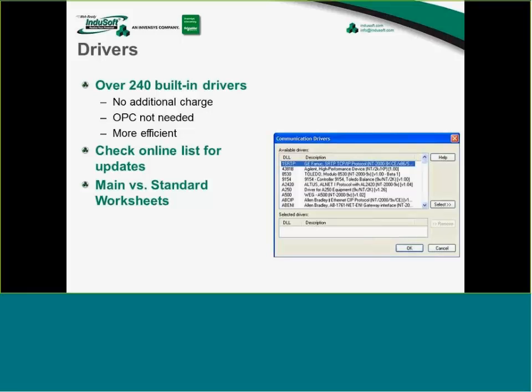It's kind of an option. We highly encourage you to use our built-in drivers and then use OPC only if it's needed for your particular application. Our built-in drivers tend to be more efficient that way and go directly to PLCs. You can check online on our website for a list of the latest drivers. I highly encourage you to do that before you start any project. It's always a good idea.